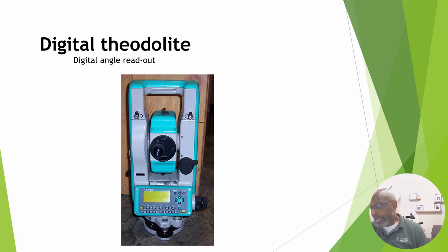However, it is a great instrument when it is working. The advantage to the contractor is that it is typically less expensive than the optical theodolite. Isn't that amazing? But here's the reason why: all the prisms that are inside of the optical. So again, the electronics brings the cost down.